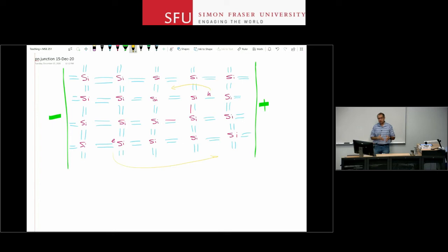And that is actually the foundation, or the reason behind the difference in behavior of, let's say, N-type transistors and P-type transistors that we will talk about later. In silicon, electrons move a bit faster than holes. Now, so far this is an intrinsic piece of material. All the charge carriers are produced from broken bonds of silicon atoms. Nothing really that interesting.